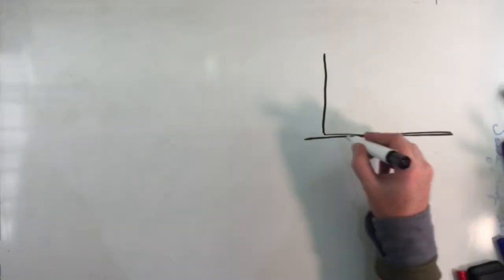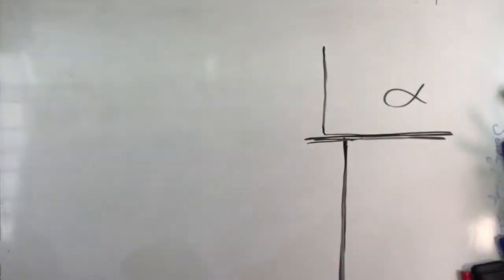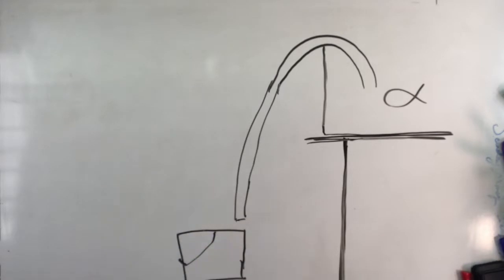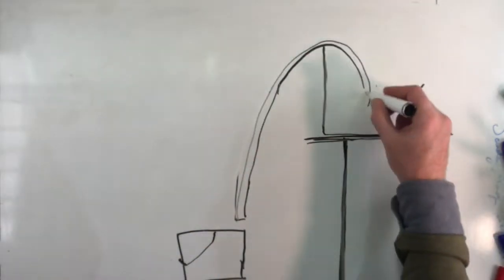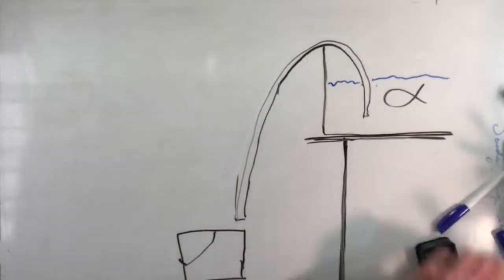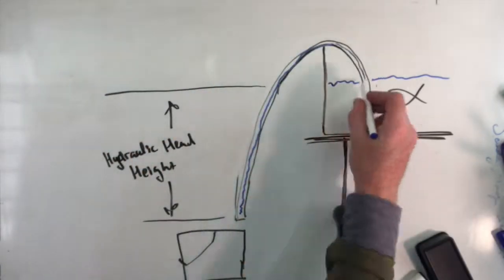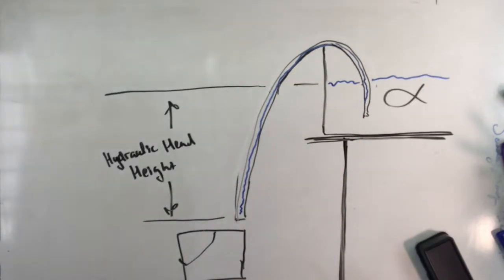The flow rate inside the pipe was determined by the level of the water in the fish tank compared to the level of the end of the tube emptying into the bucket. This distance, also referred to as the system's hydraulic head height, determines the flow rate because it is the tug from the water in this part of the system down towards the Earth's center of gravity that overcomes the water in the tube's resistance to the flow. The water in the U-shaped portion of the system is also experiencing a gravitational pull down, but the pulls from the two opposing sides cancel out.